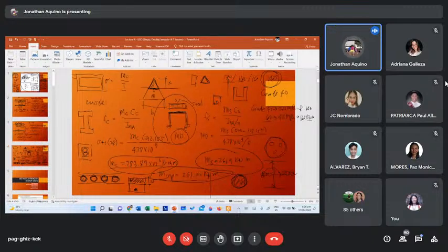Because in bridge design, it's more on reinforcement. The contribution of the strength of concrete is very small, because although it is a compression member, during seismic, flexural governs the design of tall bridges. And it's also the same with high-rise structures, the ground floors, you can mix them, okay?